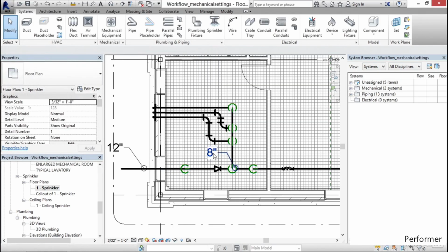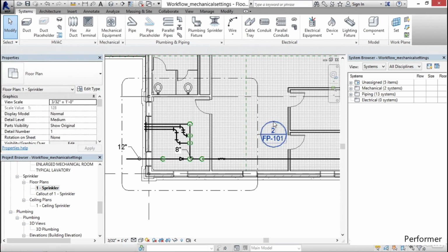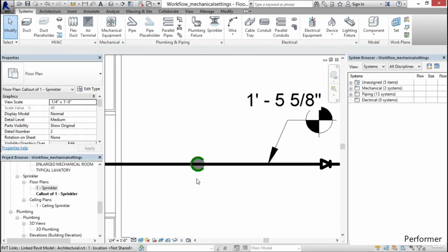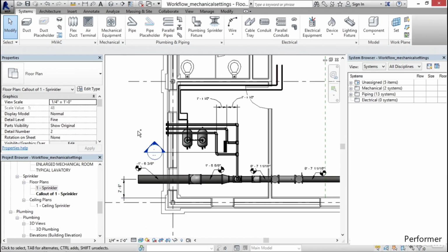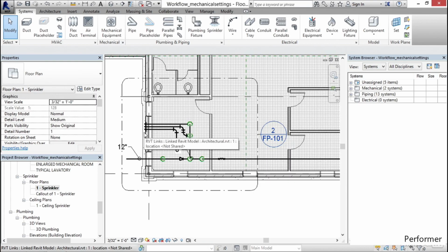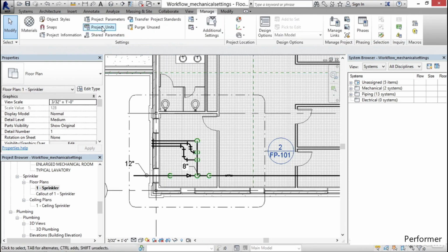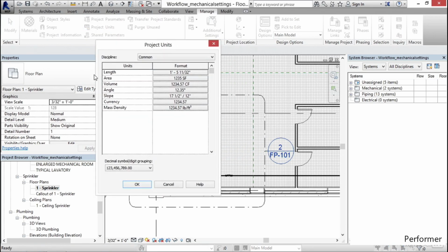Right click on the leftmost line and create similar. This time instead of wide lines, let's go with thin lines. On the Draw panel, click your Pick Lines button. Let's give it an offset of 6 inches. Let's repeat that down here. Let's hit Escape a couple times. Right-click on the bottommost line and create similar. On the Draw panel, click your Pick Lines button.